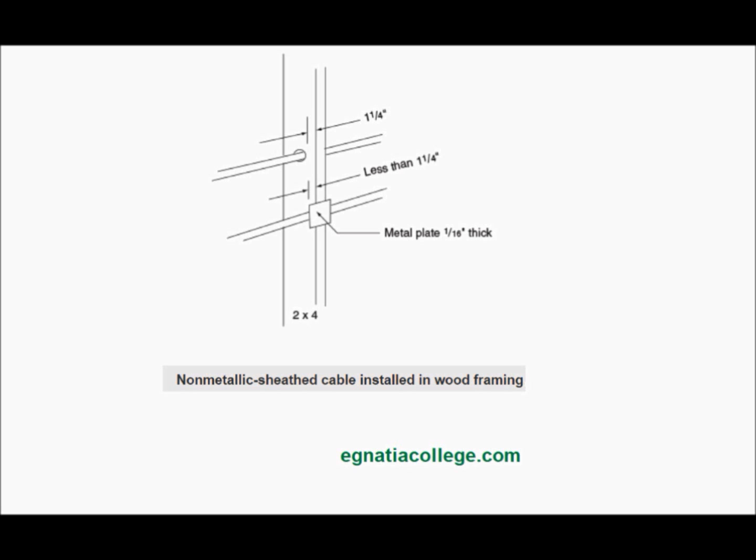This allows room for more insulation in the wall. Also notice that the house is sheathed with 3/4 inch insulation sheathing. Interior partitions do not need insulation, and so they are framed with 2x4.